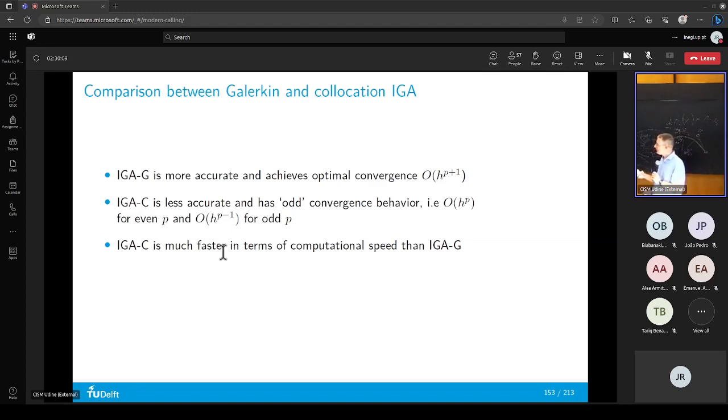And I don't mean now to refine. Refine we can always do, but you could also say I do Galerkin and I use a single point quadrature rule. If I have a sixth order polynomial, you will under integrate. You kind of make a huge quadrature error. Well, something like this is playing with the control points.